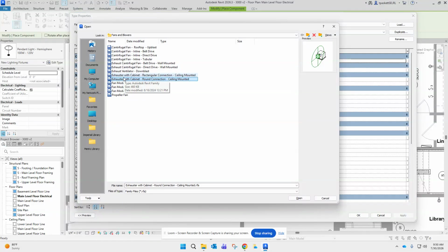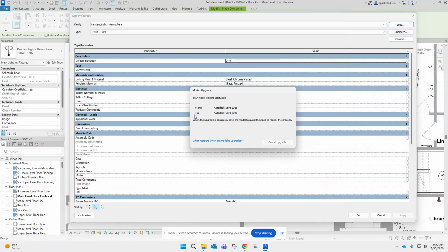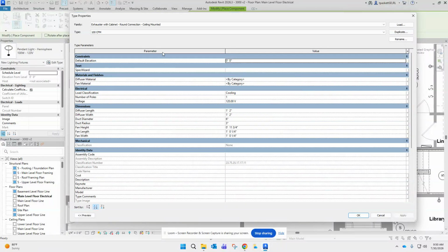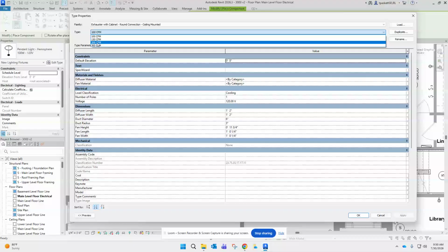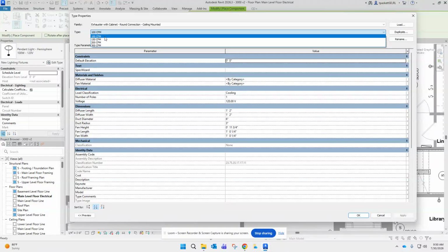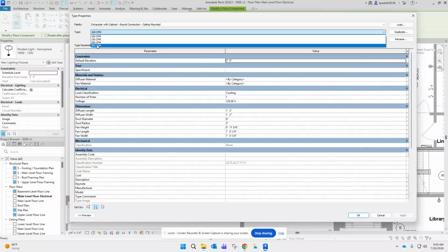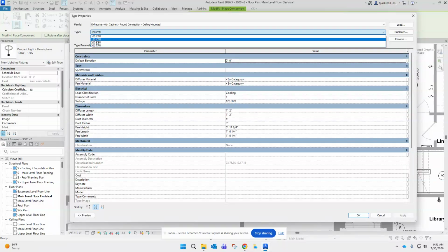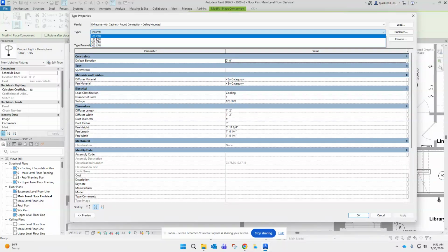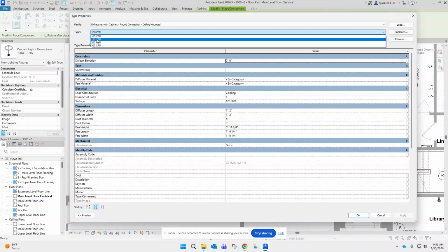So we got rectangular, round. I'm going to do a round one. I don't know why. It just seems loaded. All right. So we got that. Now, these fans, this is cubic feet per minute. In a public restroom, it's actually higher than this. I think it's 350 cubic feet per minute that have to be changed out to cycle that air. In a house, they let you go with 100. If you want a bigger fan, do a bigger fan. It does help to get the humidity out of the room as well.